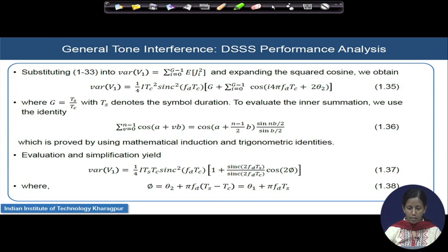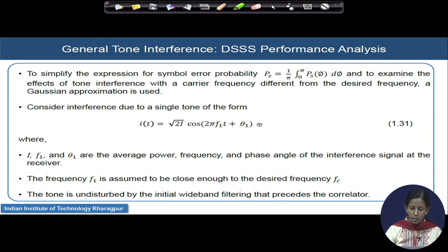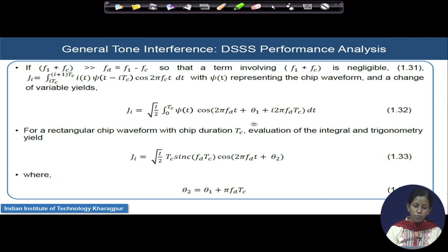If I substitute the expression of I t from the previous slide and make a change of variables, especially substituting small t as t plus i Tc, we end up here. This 2 is contributed because we have considered 2 cos a cos b; to consider 2 cos a cos b, we entered a 2 inside the integral, so we need to divide by another 2. Fundamentally, the interesting part is where the contribution from the difference term of the two frequencies plays a good role.